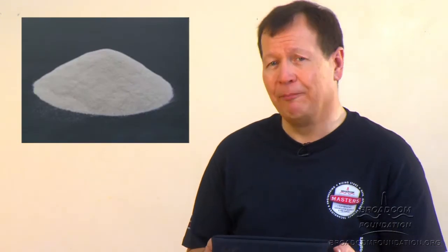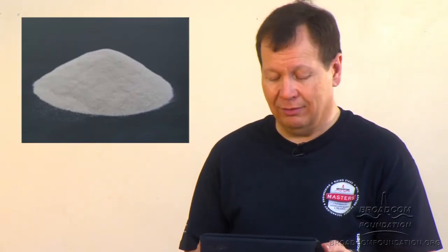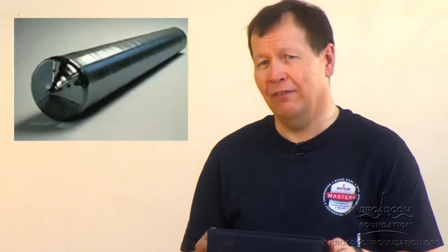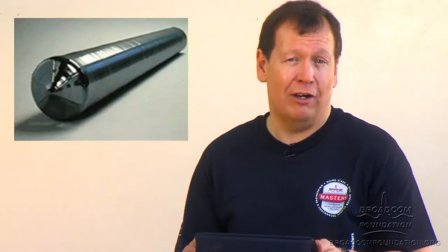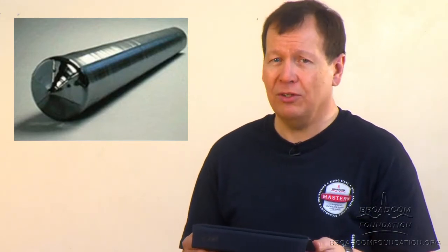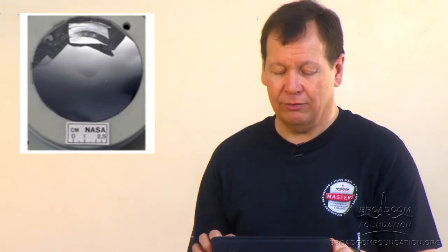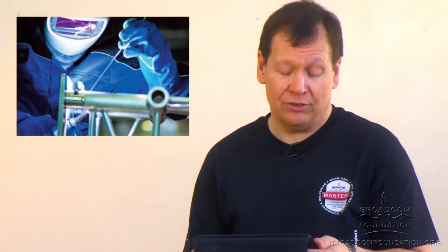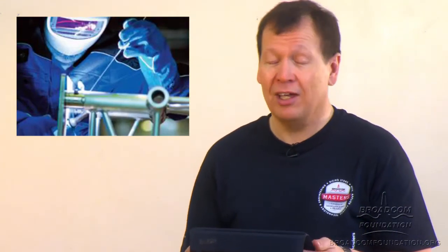Well, we start with sand, and there's lots of sand available. It's not going to run out anytime soon. We take the sand and it's refined into silica, which is usually used for making glass. But if it's refined further, we can make single crystals of silicon out of it. And these crystals, as in the picture, are about 2 meters long and 30 centimeters across. And then we take that crystal and we slice it up into wafers. Now, just to make this base material requires chemists, metallurgists, material scientists, crystallographers, and many other engineers and scientists.